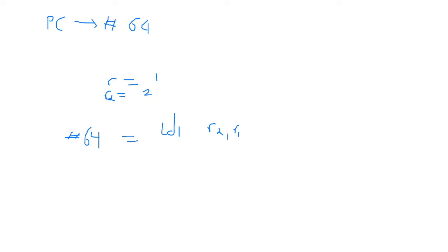But when we got to this point, there is maybe a function called subroutine 1. So subroutine 1, we get it, right? So when we get to address 63, it calls a subroutine and assigns it to a variable there. When it gets to this point, the program counter is already pointing to 64 as the next line, but this is the wrong instruction to be executed. Maybe subroutine 1 needs to get loaded into the stack.